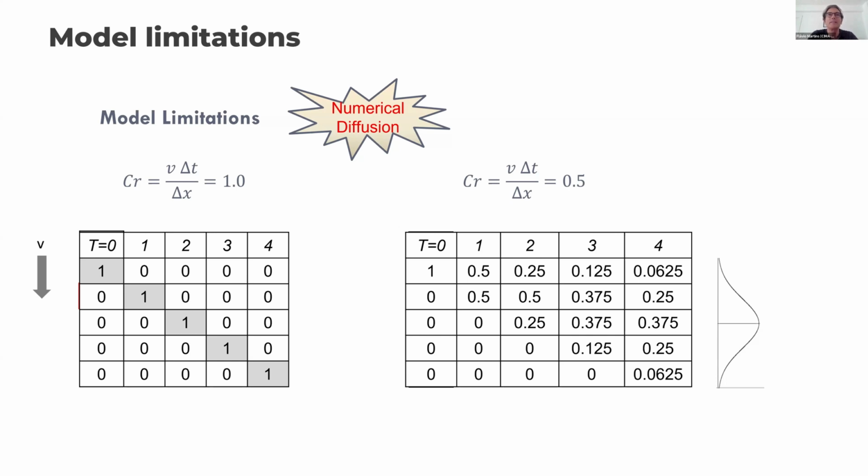And we compensate the numerical diffusion during the calibration process. One of the parameters that we usually use in the calibration process is the diffusion coefficient. Those diffusion coefficients are tuned using measurements, and when we tune them, we are already taking into account the numerical diffusion. So usually there is no big problem with that.